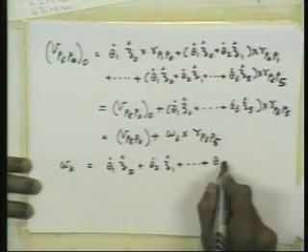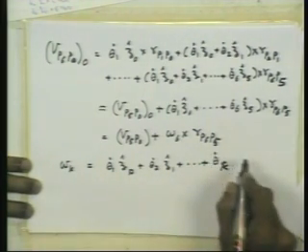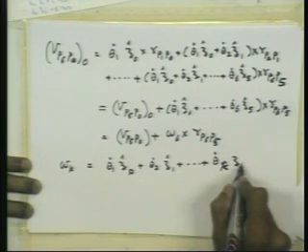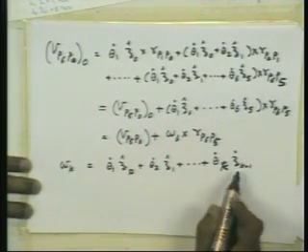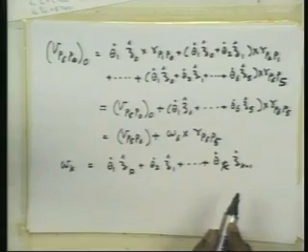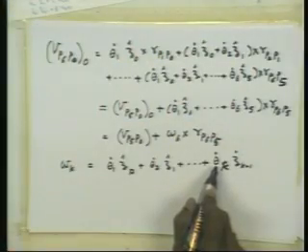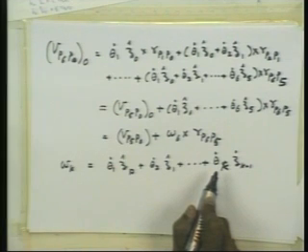Theta k dot. Remember, Z(k-1) is the axis along the kth joint. The way we set up the reference frames, the Z(k-1) axis is along the kth joint. That is why it multiplies the kth angular speed, the derivative of the joint angle of that particular joint.